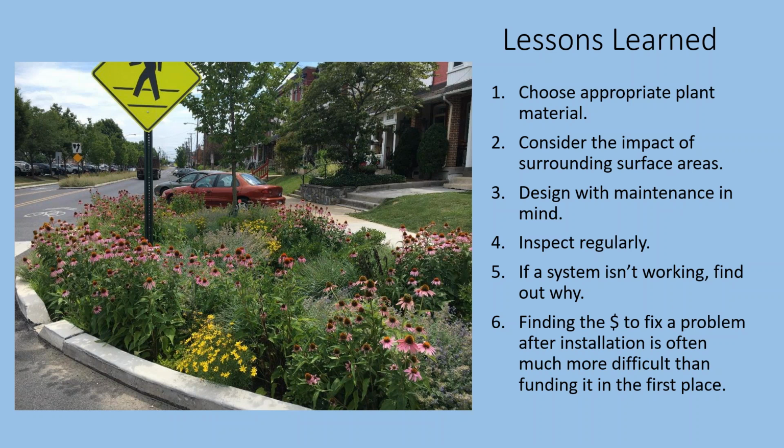Making sure that you're looking holistically, not just at the block your project is on, but at the entire drainage area. When you're doing your designs, design with maintenance in mind. Always try to get the opinions of the people who are going to have to maintain this in the field at the end of the day.